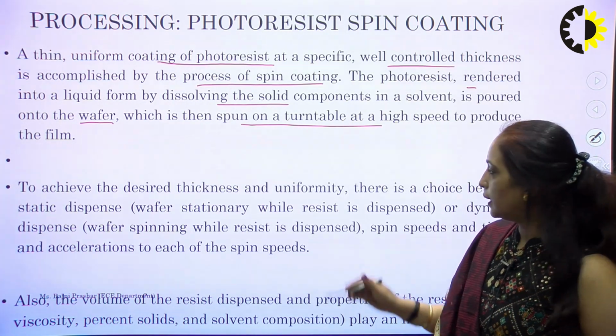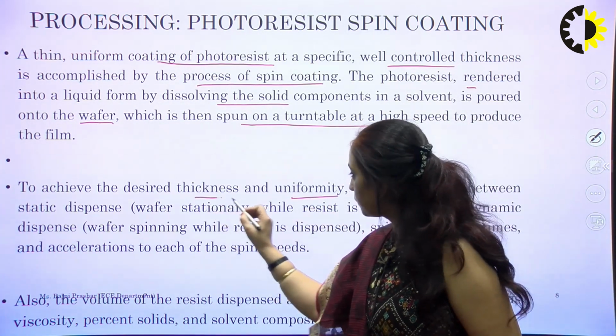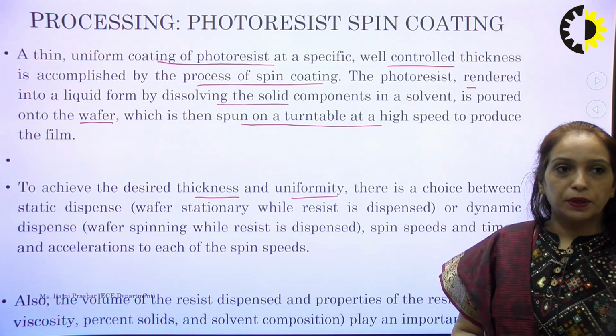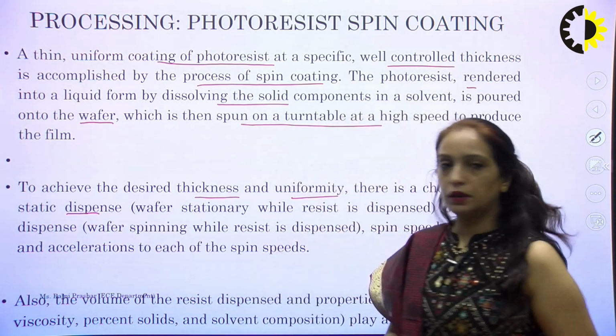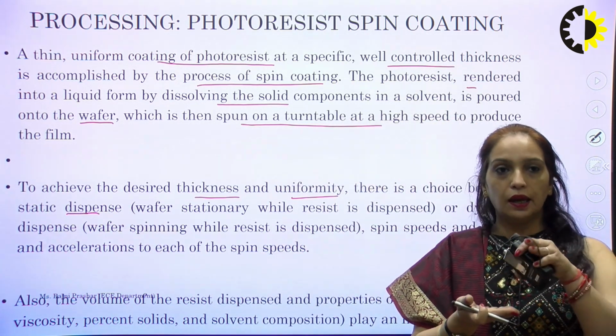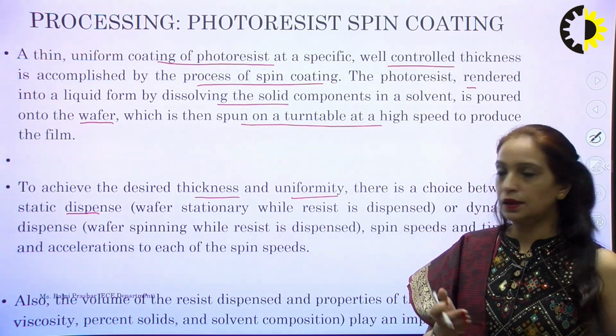Now to achieve the desired thickness and uniformity, there is a choice between static dispense and dynamic dispense. In case of static dispense, your wafer will be stationary and your resist is dispensed all over the substrate.